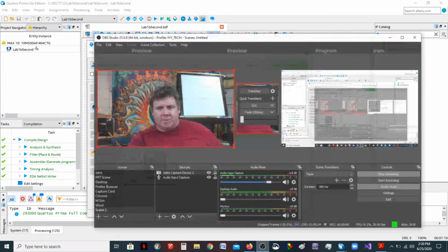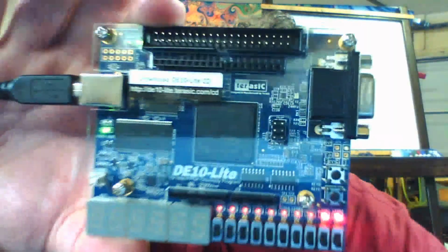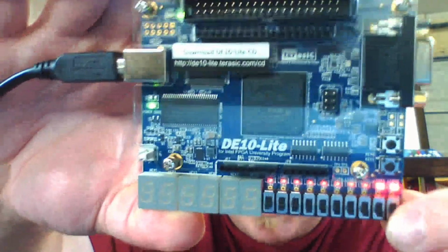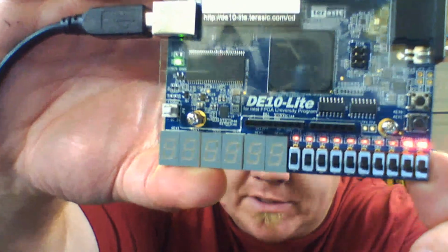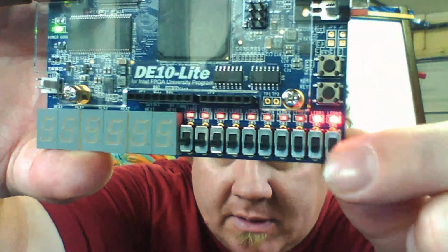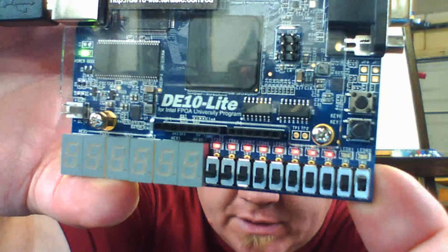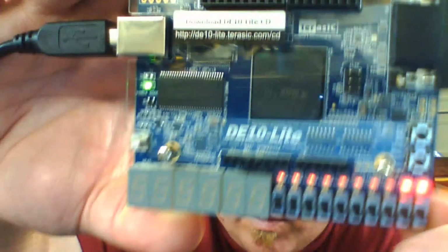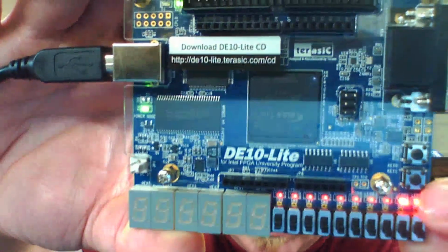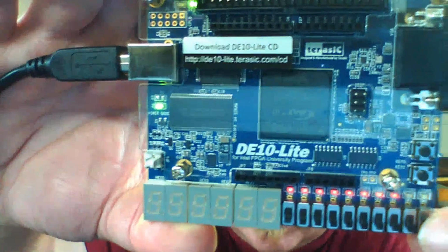Now, switch back to my camera here. Okay? With those two pins, those bottom two, right? It's just the one switch, right? I just have the one input now. But it's turning both those outputs on and off. So that's low on the switch, you can see. That's high, and it inverts it, okay? So both of them are performing the exact same function. If you told me what is behind LED 1 and LED 0, I would say there's some kind of inverter, all right? Any questions?